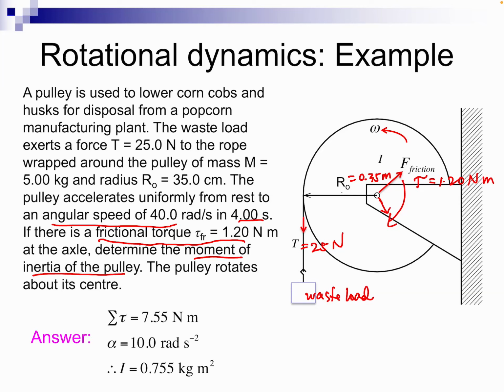A force drawn through the center would not have any effect on the rotation, right, because of the moment arm. Yes, that is a good point. So the friction should have been drawn somewhere here, not through the center. Yeah, good point.